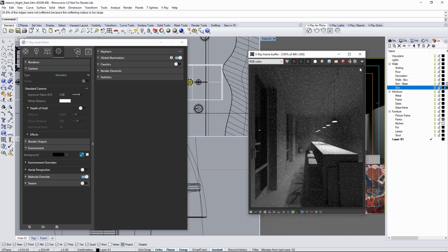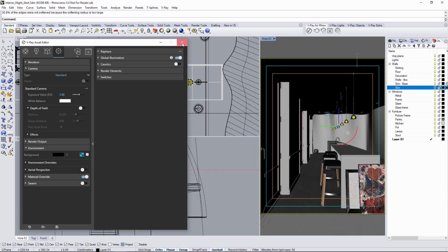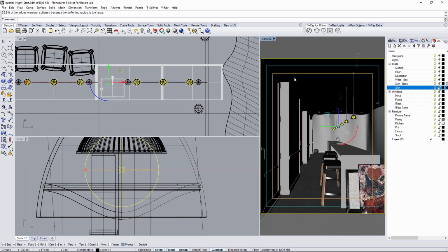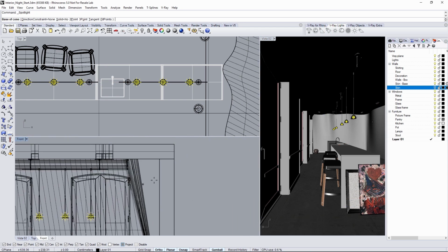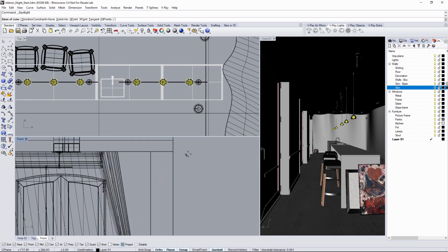Stop the render. We'll use an IES light, which uses an IES profile to define the look of the light. For more on IES lights, see one of our previous quick start video tutorials on exterior nighttime lighting. Click on the IES light icon in the toolbar, and in the front view, move over to space outside the geometry for now, and then click once and drag to define the size, and then move the mouse up to define the direction and click to point the light down.